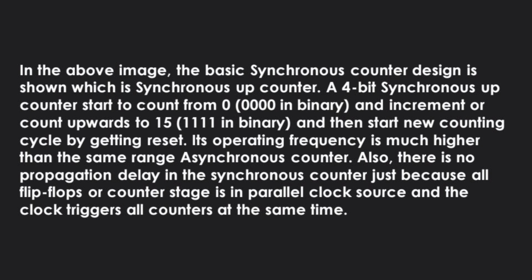A 4-bit synchronous up counter starts to count from 0 and it increments the count upwards to 15 and then starts a new counting cycle by getting reset. Its operating frequency is much higher than the same range asynchronous counter. Also, there is no propagation delay in the synchronous counter, just because all flip-flops are connected in a parallel clock source and the clock triggers all counters at the same time.